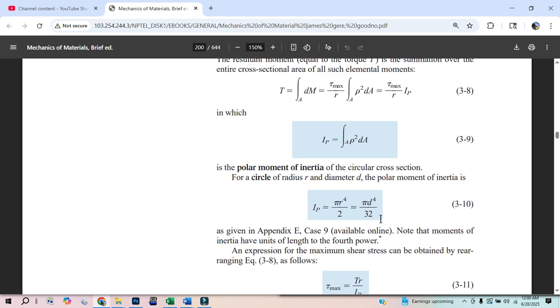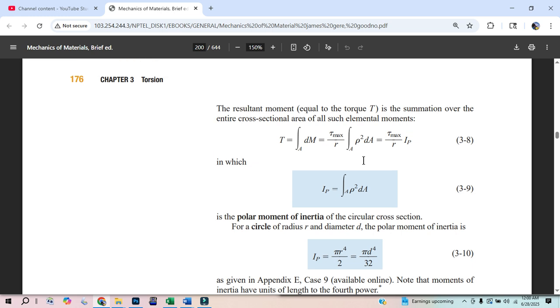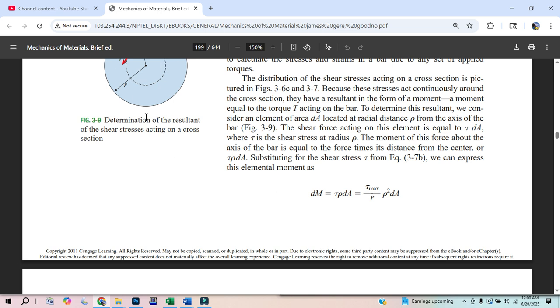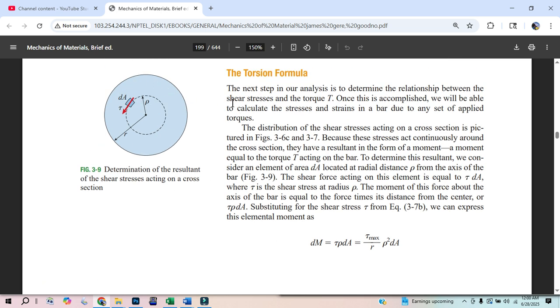So just for a cylinder, these are just given, and like I said, once it's manufactured, this polar moment of inertia is constant. That's where the light bulb goes on for a lot of these: if you ever get down to rho squared dA, you know what I mean, just throw in this big old constant polar moment of inertia. That's why it's so good to do tapered problems, because it'll change along each slice. But for this one, each slice does not change. If you have two slices of this shape, that value just remains the same.